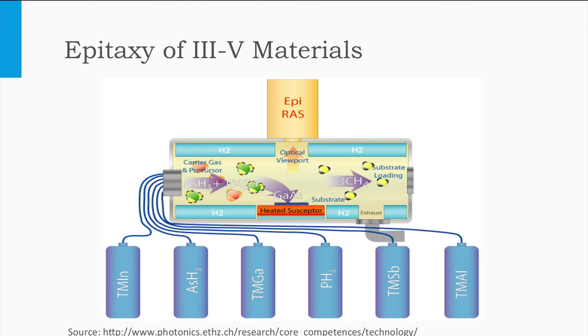In general, metal organic chemical vapor deposition, abbreviated as MOCVD, is used to deposit the 3-5 semiconductor layers. Typical precursor gases are trimethyl gallium, trimethyl indium, trimethyl aluminum, arsine gas and phosphine gas. Surface reactions of the metal organic compounds and hydrides containing the required metal chemical elements create the condition for the epitaxial crystalline growth.